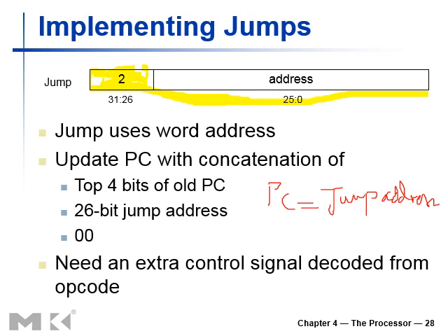So definitely this is a memory address. First of all, we have to multiply it by 4. Multiplying by 4 will make these bits 28, because we are left shifting the data by a factor of 2. So these 26 bits are converted into 28 bits, and for the rest of the 4 bits we simply concatenate the program counter's most significant nibble with the address.